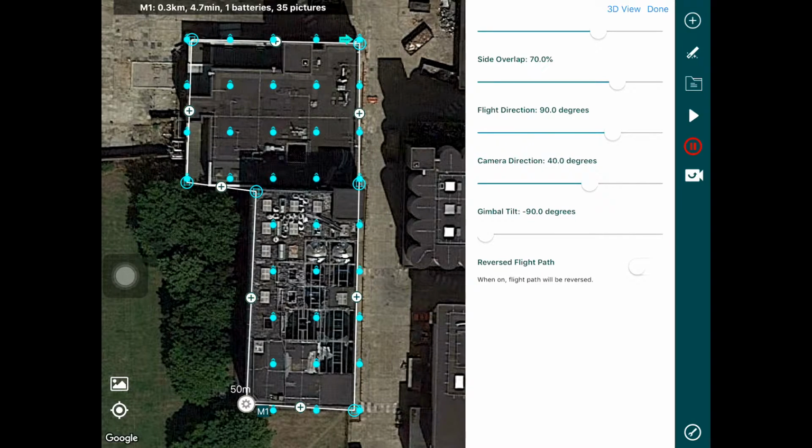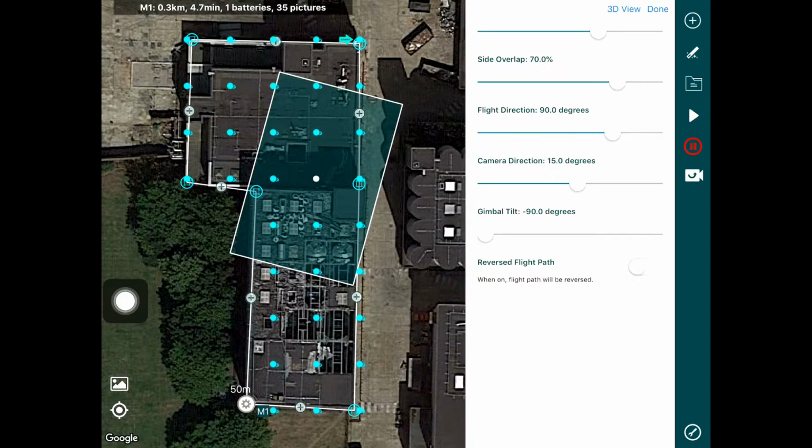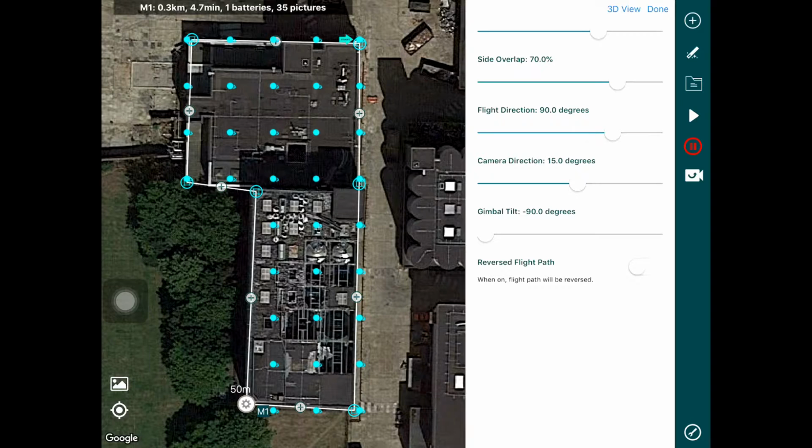We know that for some of the solar inspection work, which is not quite what we're discussing here, we're discussing the roof inspections, but for solar inspection it's quite important sometimes to orient the drone in a different way and to fly in a different direction. So in this particular example right now, the drone would be facing east, but would be flying south in terms of its navigation itself. Those are, again, settings that we can configure for the flight. Let's say we're actually going to keep it in the direction of the flight, so 90 degrees for the camera direction as well.